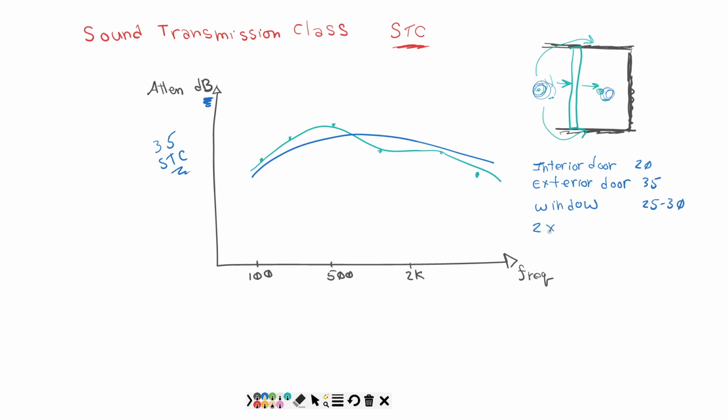So a standard, let's say 2x4 interior wall, you're probably looking at, again, depending, do you have 1/2 inch or 5/8 inch drywall on it, stuff like that, somewhere maybe 35 if you're lucky, 30 to 35, let's say, for an STC. And like I said, when you're up around this value, 35, somebody can be in the other space and you can tell that they're having a conversation. You just can't hear it very well, right? These are going to be insufficient if you're really looking to make something that has some acoustic isolation.